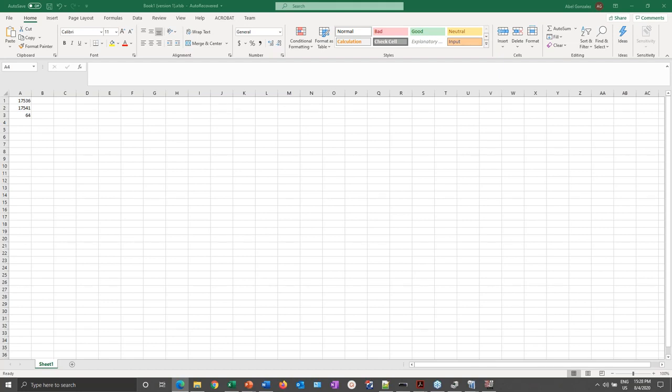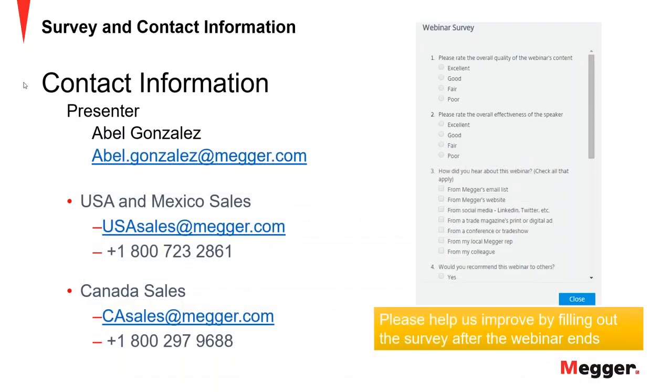If you need to change to an alternate group, group 2 or 1 through 6, however many groups the actual relay has, then each group can be classified as a relay. So you would read group 1, test your relay, and then save that information and result and template off. Then your second group is the same relay, just a second group, because all the settings are still available to you in that second group. You just have to classify it as group 2 of the same relay, and so forth, until you complete all the groups that you need tested. So yes, you can do that.